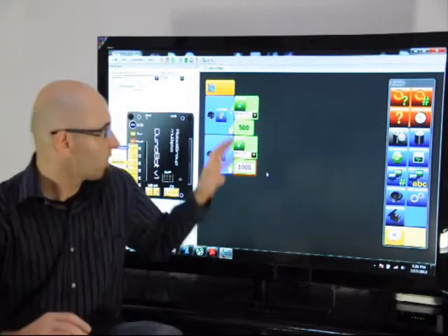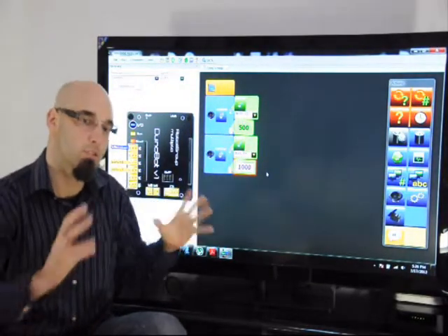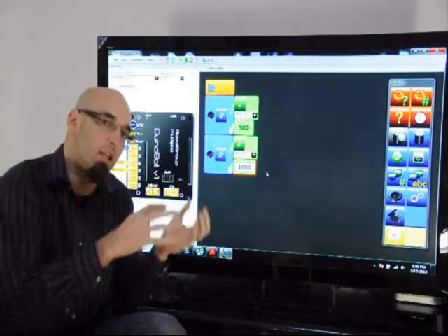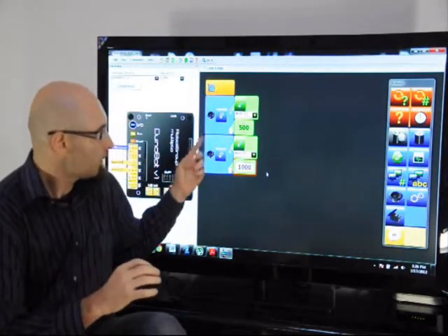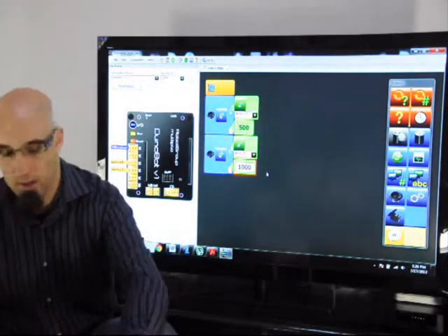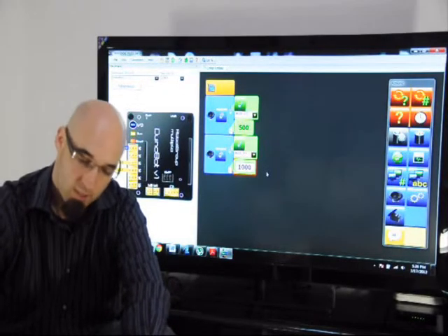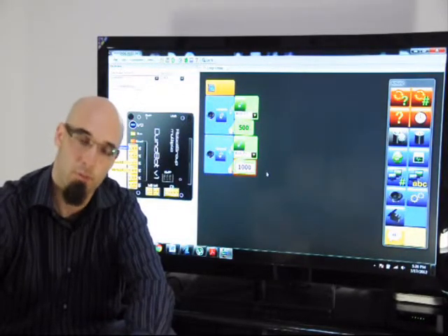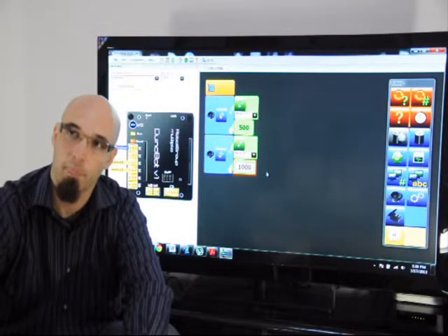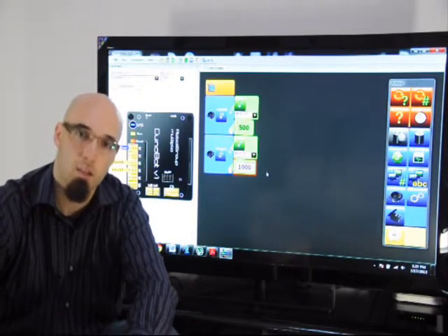We've already programmed this. Now we're going to make it compile this. So compiling is translating into machine language, and then upload it into the board. Now you're going to see that the board is ready to accept information. Once that we're uploading and programming the information into the board, it's going to start blinking. But it's not until it stops blinking that it executes.